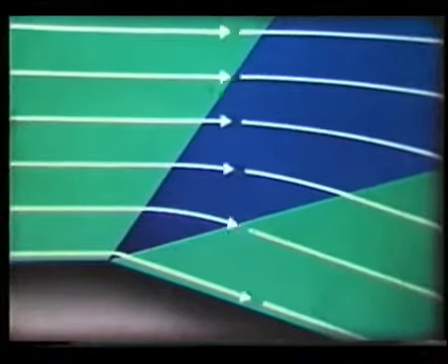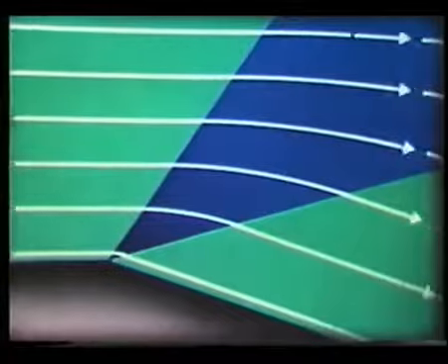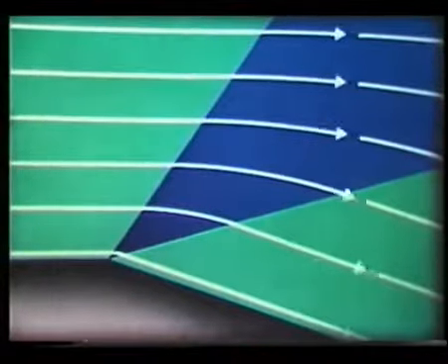Inside this region, pressure, direction, and speed change smoothly, unlike the shock wave case, where there's a sudden change in direction and pressure. But in both cases, supersonic flow wheels round to follow the new surface with little disturbance. Here it is obstructed and so slows down, whilst here it's been helped on its way, so it speeds up.